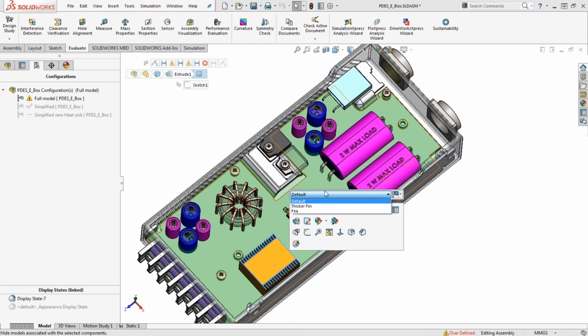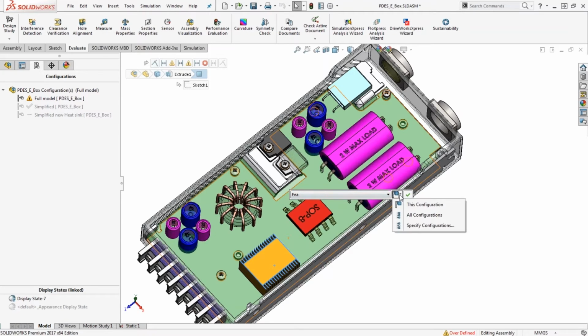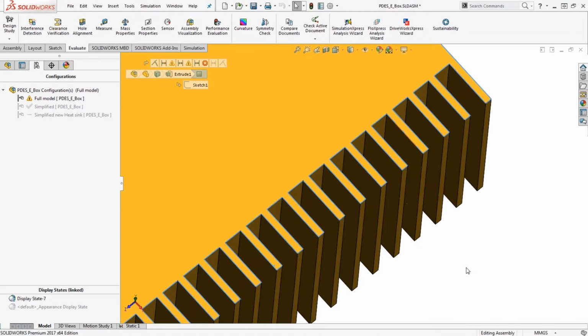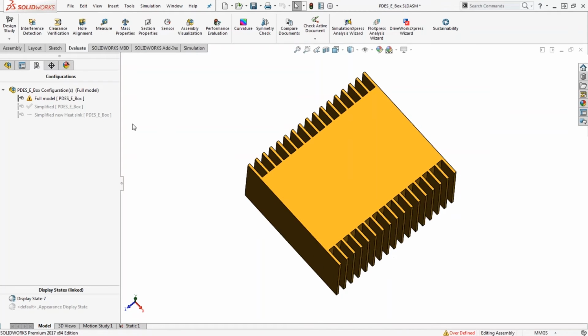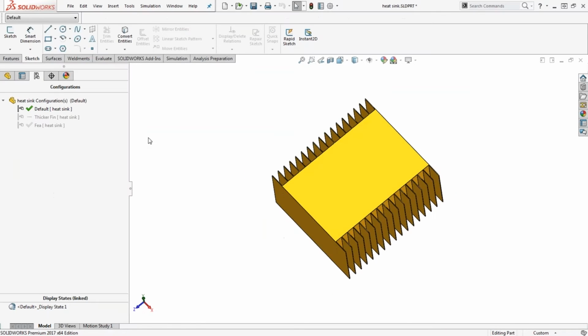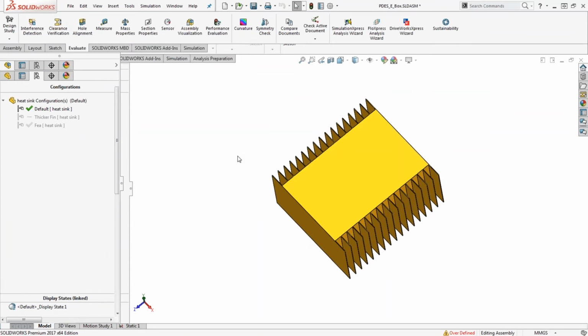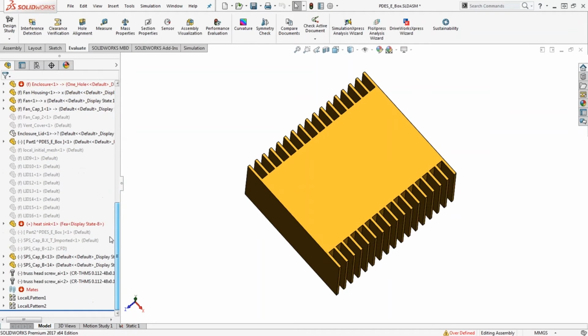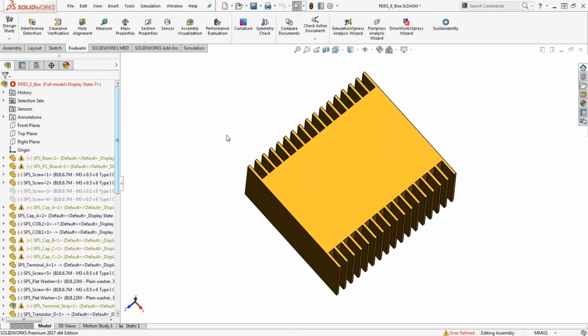But now that you have multiple configurations within your part, you can go into your assembly, select that component, and then switch it to whatever version you have. Right now I'm working in the full model, but let's say this was the actual model that I wanted to run that analysis on. Well, I can go into that configuration and then switch my part configuration to the FEA. Note that you have the same option at the assembly level. It's recognized, and I say I want this specific assembly config to be linked to this part config, and you can say this configuration here, hit OK.